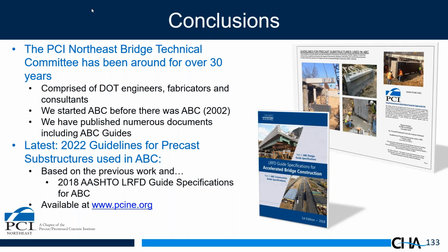So I keep saying it, we haven't seen any issues manifested in the field. As far as grouted couplers, one of the earliest bridges built with grouted couplers is in Florida. It's called the Edison Bridge. I'm saying 30 years ago. It's been out there forever over a saltwater bay. This thing, it's a corrosion experiment with a highway on top of it, and it's performing well. So we have a lot of track record on these connections, and they really do perform every bit as good as cast in place.